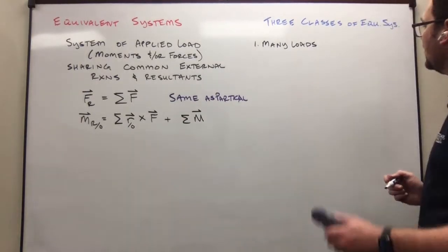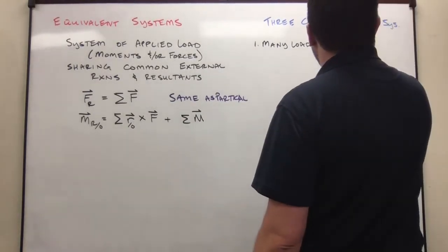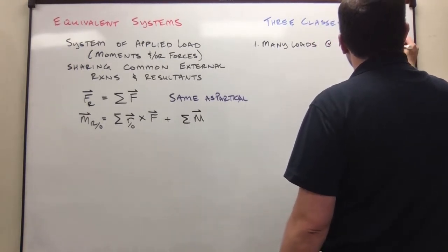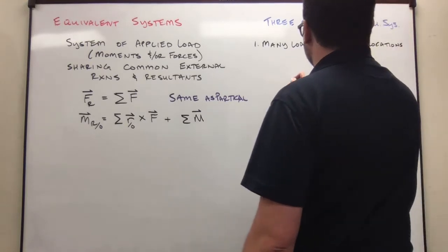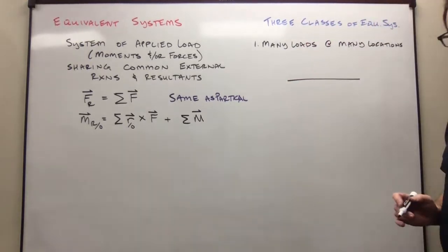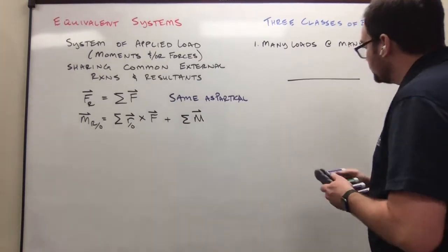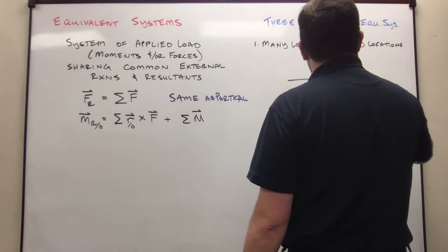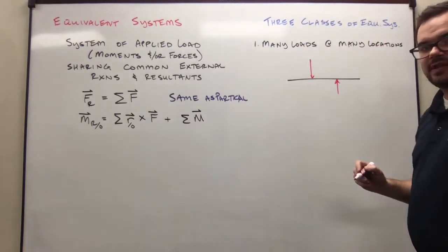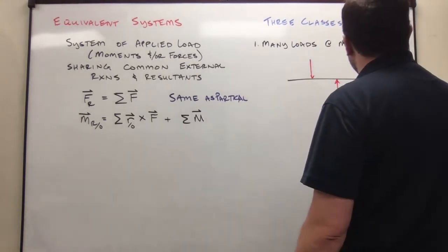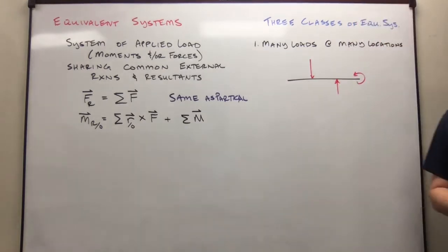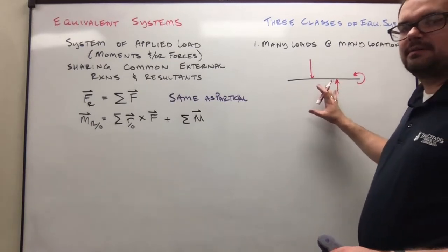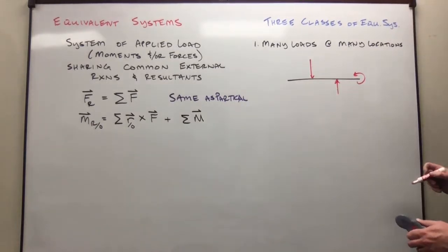And so if I were to draw a sketch of that, this is at many locations, this would be something like this. So maybe I've got a beam that I'm designing, and it's got a ton of loads being applied to it. So maybe there's some gravity loads, maybe there's some uplift pressures like earthquake loading, maybe there's some other beams that are causing moment to be applied at the end, all sorts of things like this. So this would be our closest to our real model of what reality would look like. So we have these applied loads.